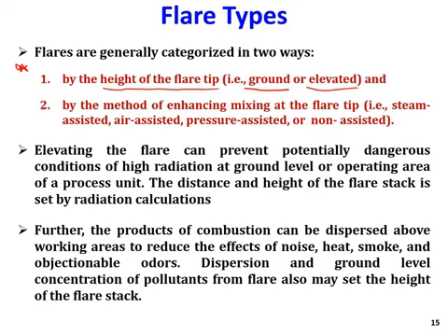And another method that we categorize them is the method that we enhance the mixing at the flare tip. So we can use steam, air, or some pressure, or non-assisted. So those are the methods that we use at the top of the flare tip. We can use air, steam, or some pressure source and mix it with that gas at the top of the flare, or we might not use anything. The flare gas is enough at high pressure that can be burned easily at the tip of the flare.